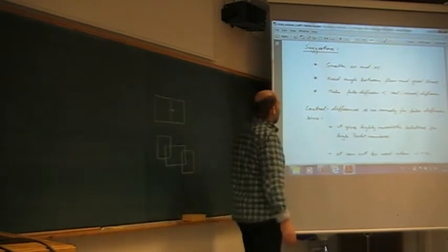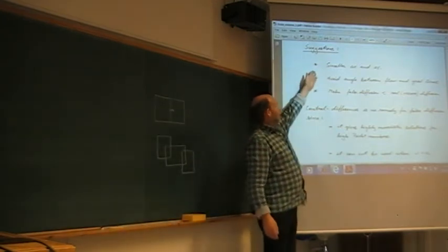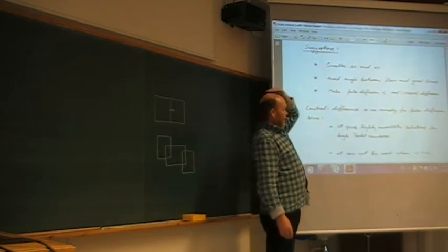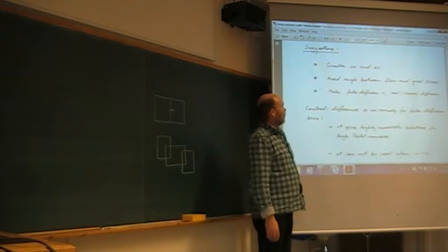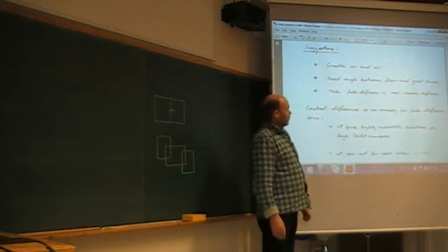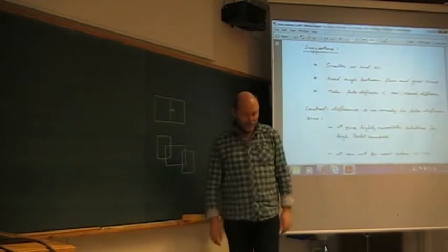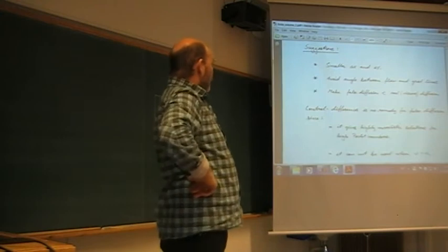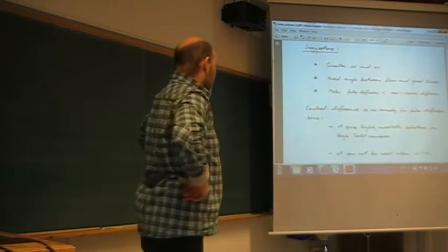What can we do? Of course, bigger computers, more delta x's and delta y's. That's one option. Also try to avoid any angle between the flow and the grid line. So if you have an angle, it should be 90 degrees. Orient the grid according to the streamlines.